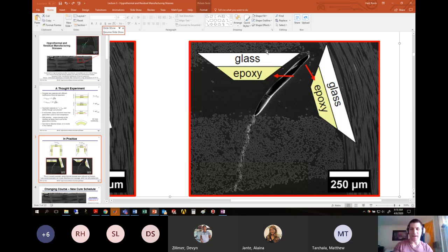And the basic idea here is that we have a series of glass fibers. Hopefully you can see them. They're kind of coming out of the paper here for this particular composite. And then we have a series of glass fibers that are coming down this direction, across the plane. But the basic idea is that the arrangement looks something like this, where we have a glass heavy region and an epoxy heavy region. So you see this black region here, that's pure epoxy.